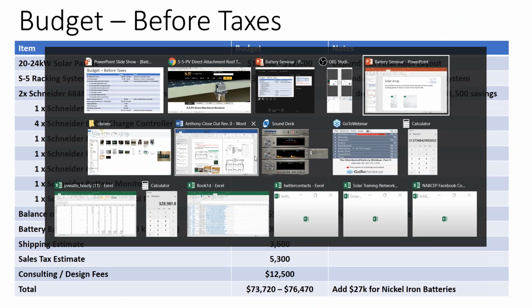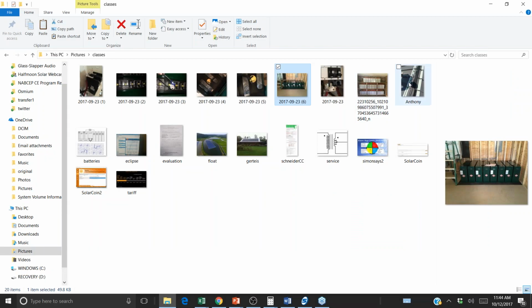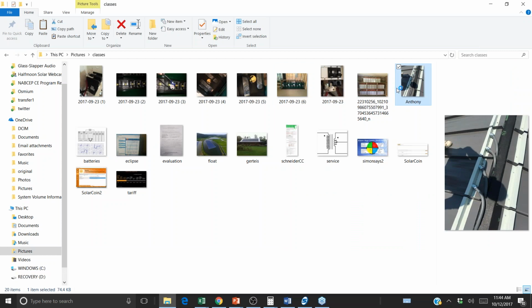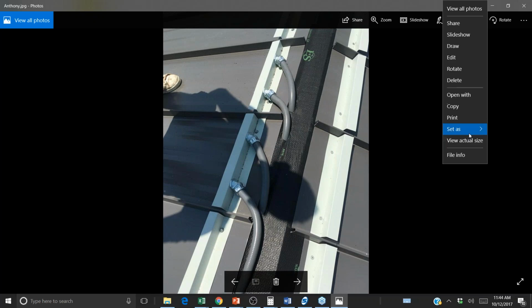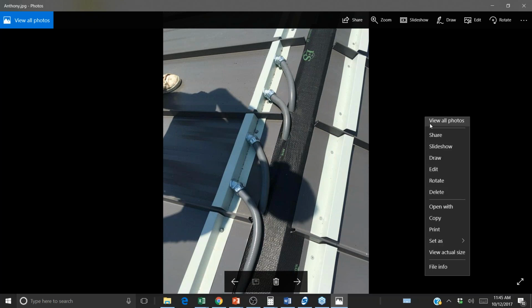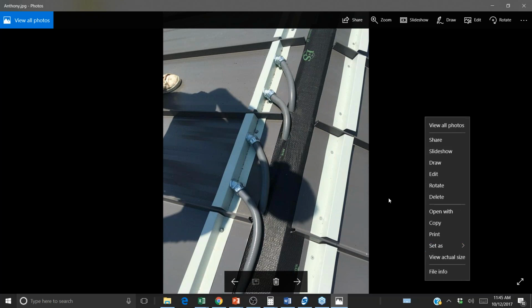Let me pull up some pictures to show you the final product. So here's what that looked like. And so we have 4 charge controllers, and with 2 circuits each, we don't have to do inline fuses. As far as rapid shutdown goes, well, we actually didn't do rapid shutdown on this project. This is in rural Mississippi. I've even done megawatt projects that don't require an electrical permit.